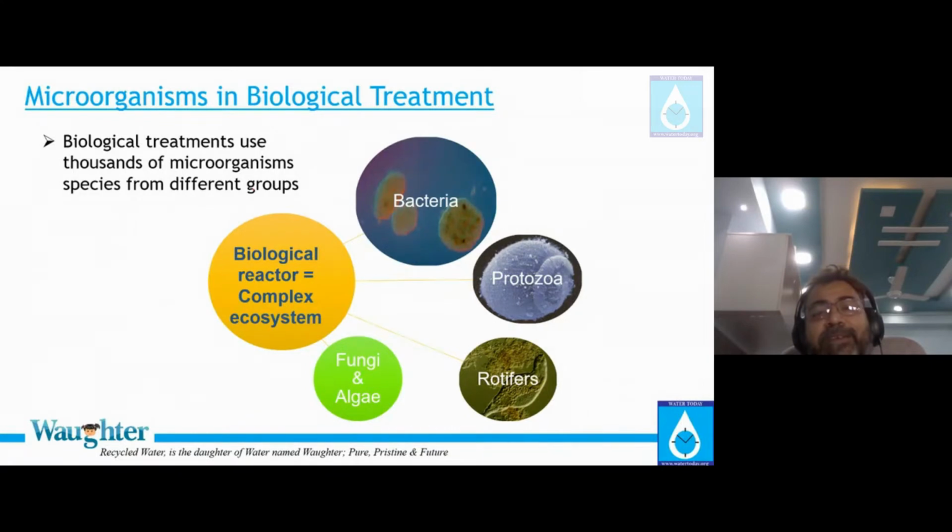But when bacteria starts growing, some of them become greedy and they feel we can eat their own population. Those materials are called protozoas. So once there is a protozoa in the system, it is an indicator there are enough bacteria in the system, because protozoas don't eat your COD. They don't breathe your COD. They feed on bacteria. Similarly, rotifers do feed on protozoas.